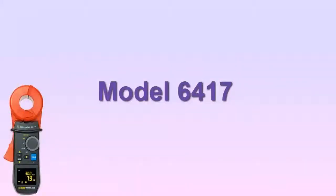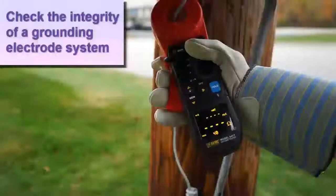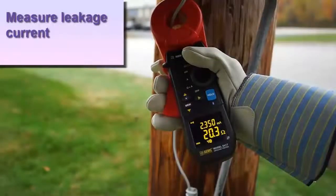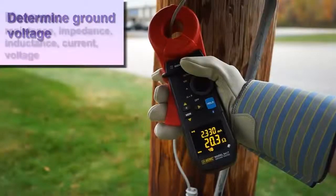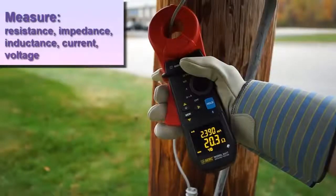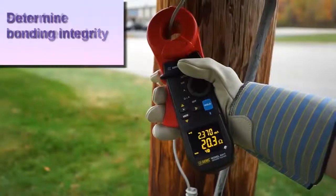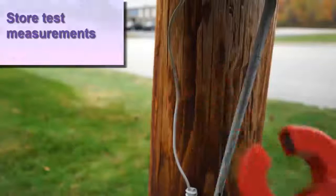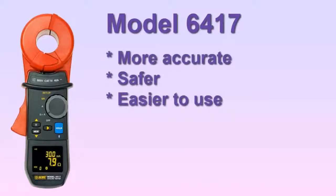The Clamp-on Ground Resistance Tester Model 6417 measures ground rod and grid resistance without the use of auxiliary rods. The instrument enables you to check the integrity of a grounding electrode system, measure leakage current into the grounding system, determine ground voltage as an indicator of a potential unsafe condition, measure resistance, impedance, inductance, current, and voltage, determine the bonding integrity of the grounding system, and store test results for later review and analysis. The Model 6417 is specifically designed to improve measurement accuracy, user safety, and operator ease of use.